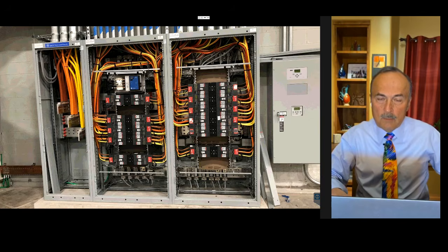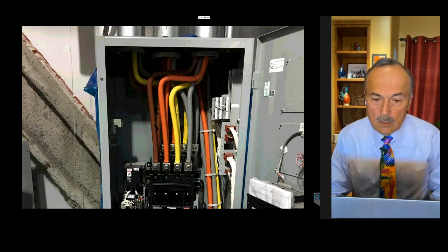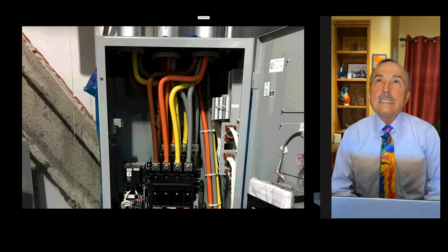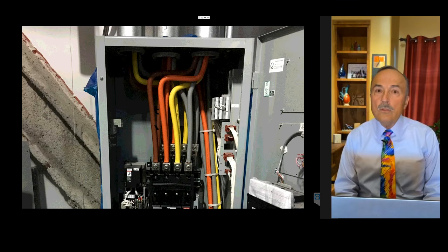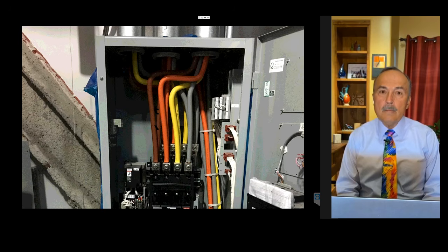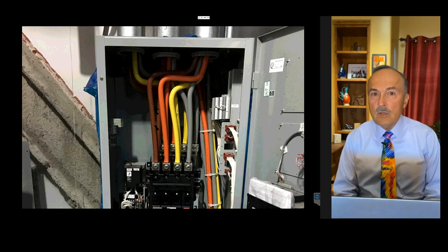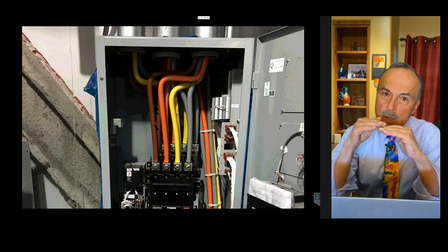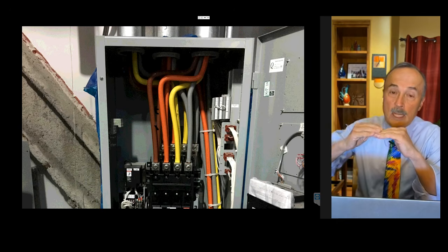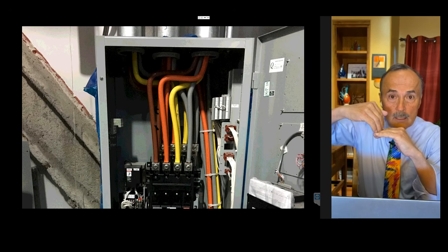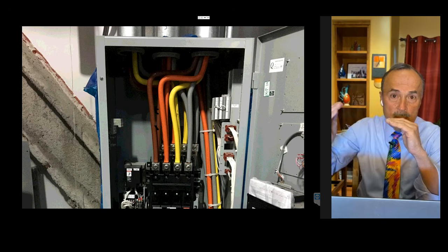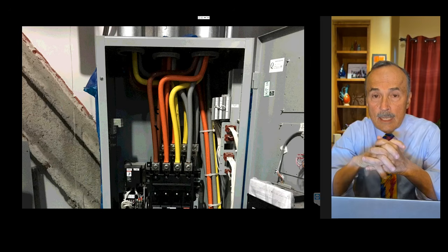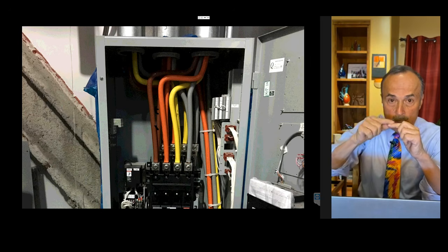Okay, a comment was, Mike, what about 312.6? There is no rule in 312.6 about wire bending. If you take a look at 312.6(A), it's talking about the distance from where the terminal is, depending upon whether you're coming in opposite the entry or not. If you're coming in from the top and going right into a terminal, 312.6(A) tells you how far that terminal can be from that enclosure.